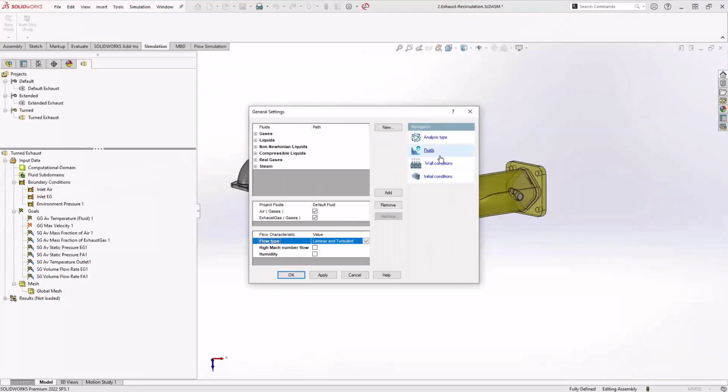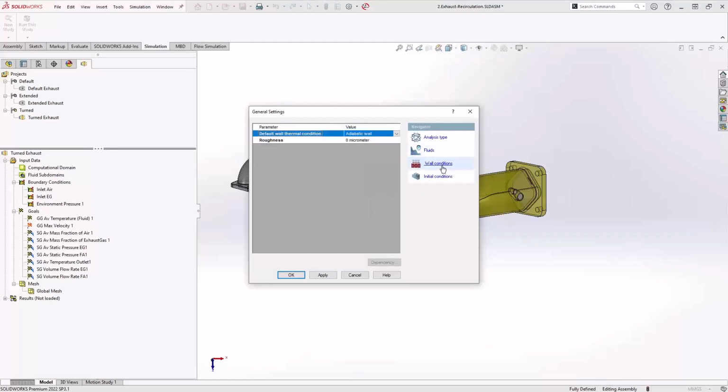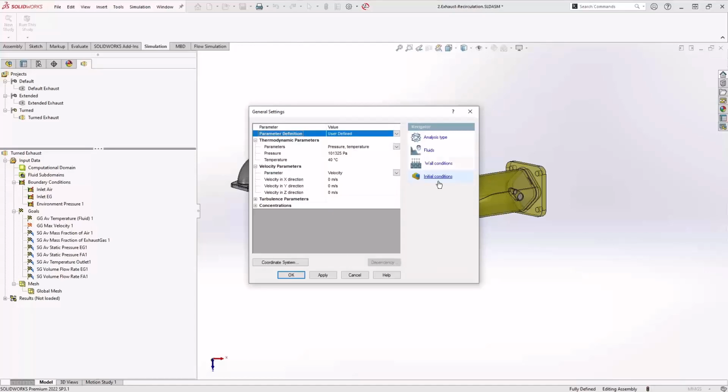All right, the fluids that I'm running through it in this case are just air and another fluid that I've called exhaust gases. There is a big material database over here called the engineering database. It houses all my materials, all my fan curves, all my filter medias, really anything I want to stick in the tree. So I've made a material separate from air called the exhaust gas that's going to be getting mixed together. I've got some default wall conditions, meaning it's adiabatic. The only way that heat comes in or out is through the inlets and outlets that I tell it. And then I've got a smooth wall, so a zero slip at the wall assumption here. I don't have a rusty pipe, but I could.